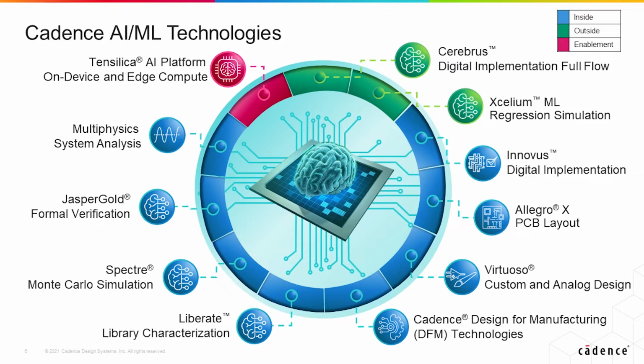Spectre X Monte Carlo. New high sigma 4, 5, 6 sigma capabilities are now available within Spectre X. It uses ML to develop an accurate surface model in order to predict extreme tail values. The algorithm produces actual Spectre simulatable points, so there is no loss of accuracy here.